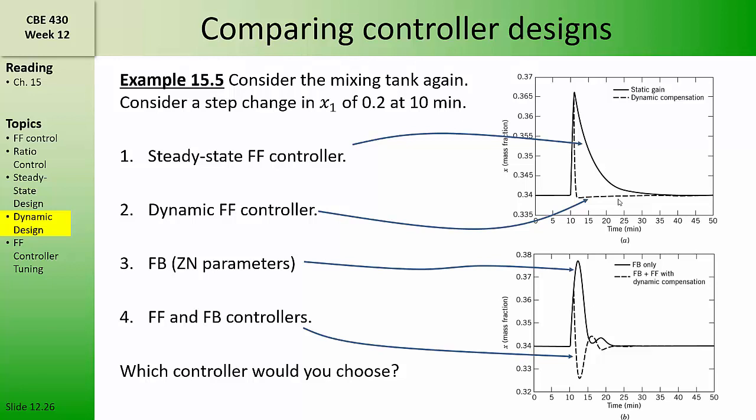We should usually combine feedforward control with feedback control, because without the feedback control, the system will not respond to unknown disturbances. And if there's any error in our model, like suppose the level in the tank is not at its design condition, then the feedforward controller is tuned incorrectly. And only by using feedback control can we ensure that the process won't drift away from the set point.